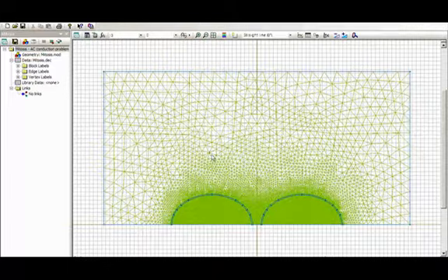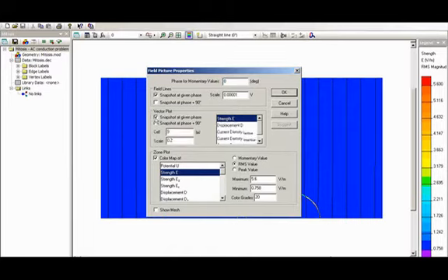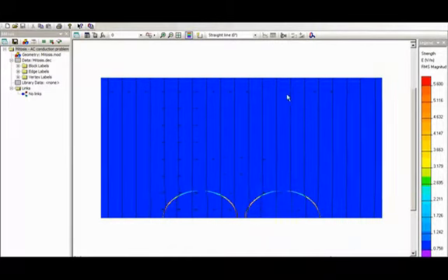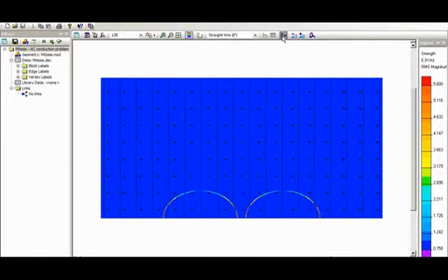Okay, loading. Now at high frequencies, you can see that the equipotential lines are now present inside of the cell, and in fact the electric field and the current are now penetrating the cell here. And I can make a plot of, for example, the electric field strength or any of the current components. Okay, so there you see the electric field. Furthermore, we can animate the solution and look at the electric field at different cycles, because this is an AC cycle, so the electric field is going to be changing direction as we excite the cell sample here. And then we can stop the animation.